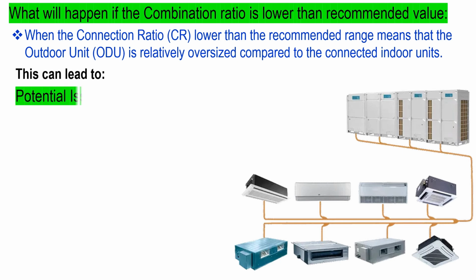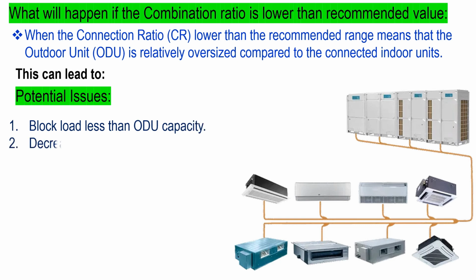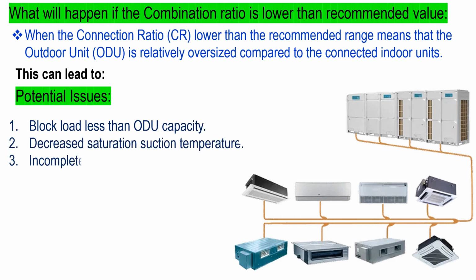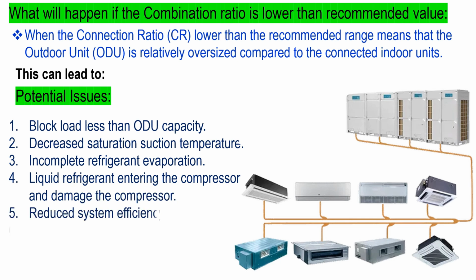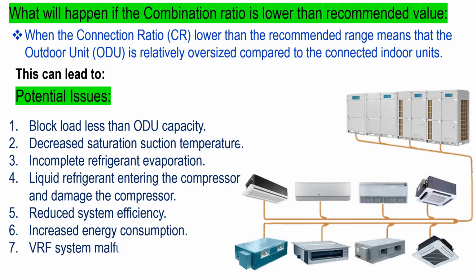1. Block load less than ODU capacity. 2. Decreased saturation suction temperature. 3. Incomplete refrigerant evaporation. 4. Liquid refrigerant entering the compressor and damaging the compressor. 5. Reduced system efficiency. 6. Increased energy consumption. 7. VRF system malfunction. 8. Shortened equipment lifespan.